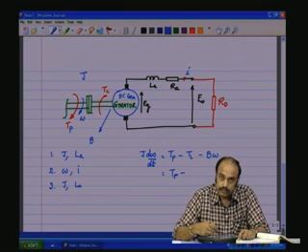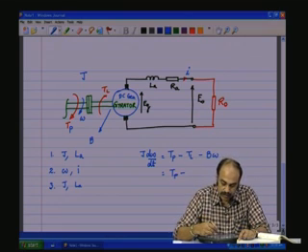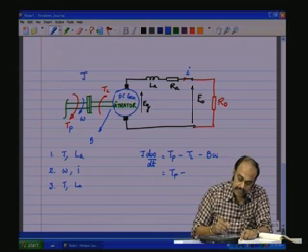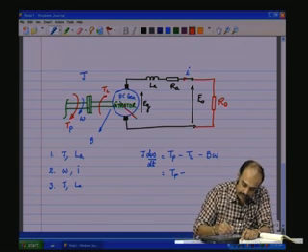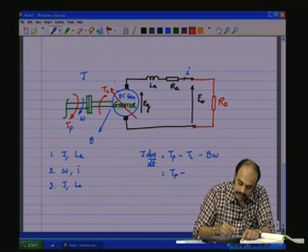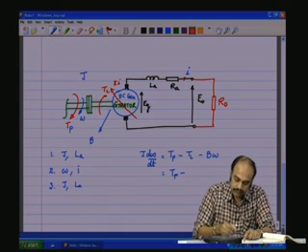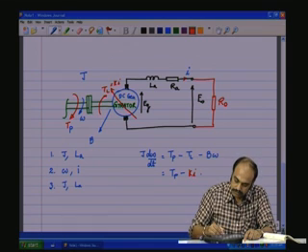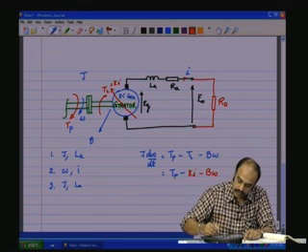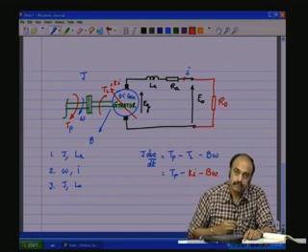Tp is the input variable. Now, TL is the load torque. By gyrator action, the link is K into i. This would be K into i minus B omega. Now, all are in the form of state variables. So, this is one equation.